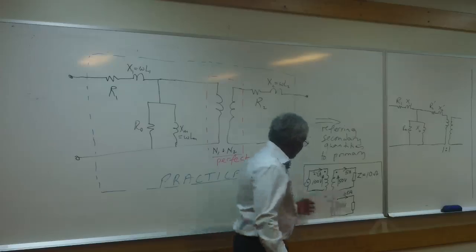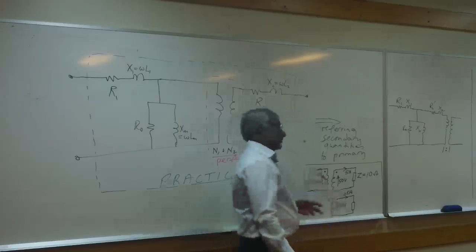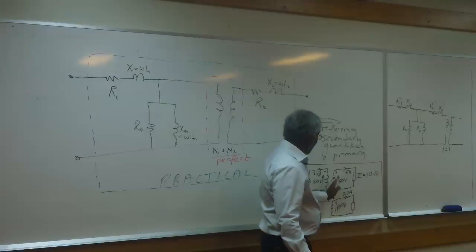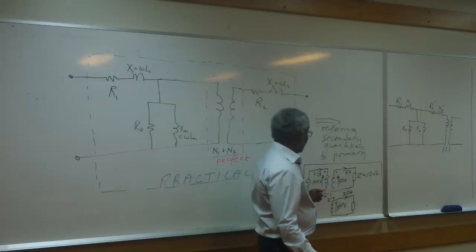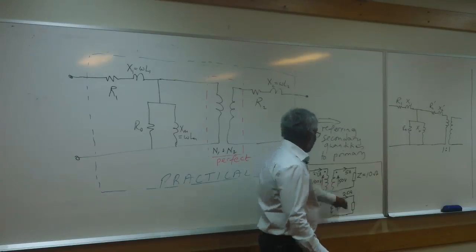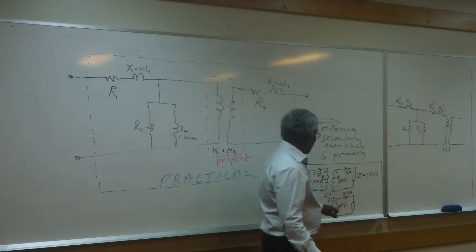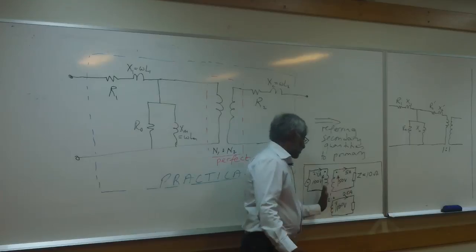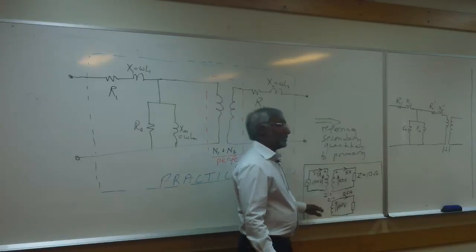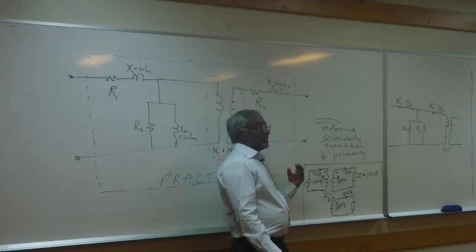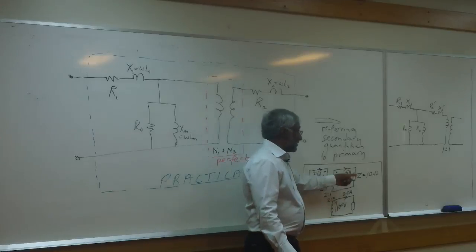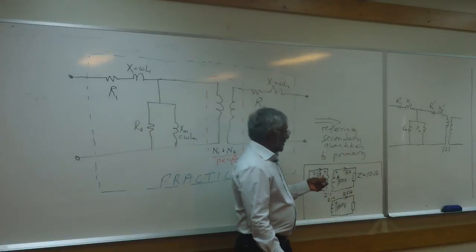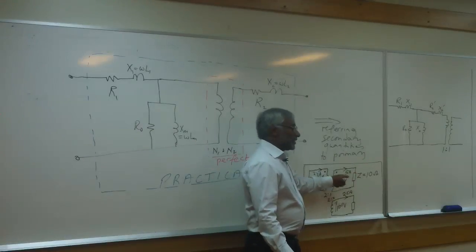And I appropriately change the impedance. And you look from this side, from the same primary, would you know any difference? Would you feel any difference if I change everything here, take it out, make it 2 to 2, which is the same as 1 to 1, and I change the impedance so that this is the same current as that side? Of course, it has to be the same because the turns ratio is 1 to 1. You wouldn't know any difference. So for the primary side, it doesn't care really what's on there. It can be a multiple of possibilities here without changing anything there.